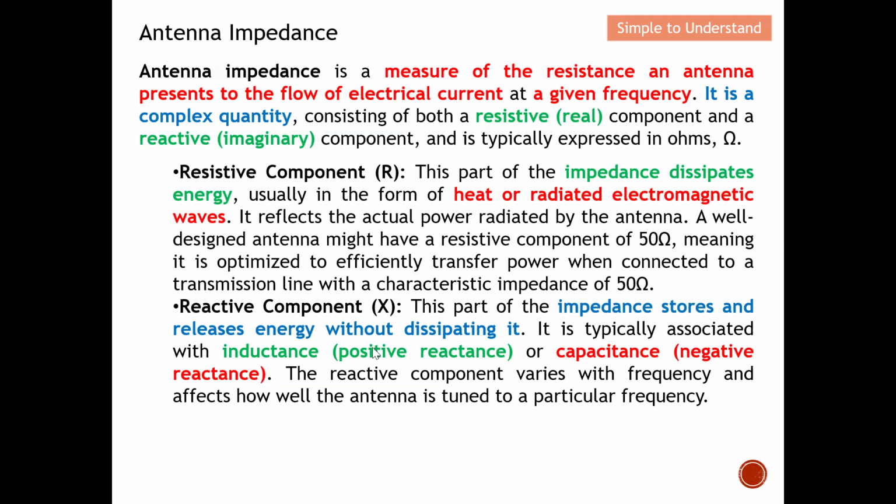As for the reactive component, which is the imaginary part, this part of the impedance stores and releases energy without dissipating it, which means they store or release it without really consuming power. It is typically associated with inductance, which is the positive reactance, or capacitance, which is the negative reactance. The reactive component actually varies with frequency, which I have highlighted many times, and this will affect how well the antenna is tuned to a particular frequency.